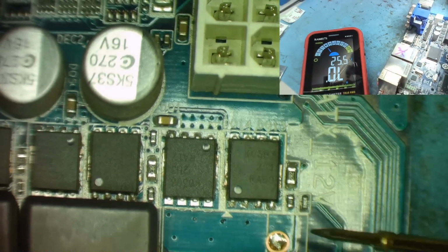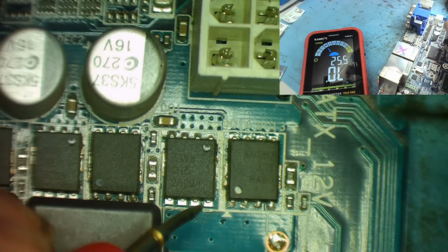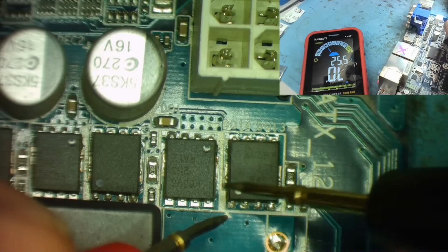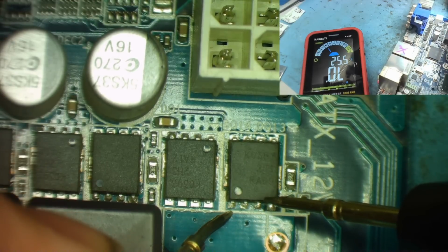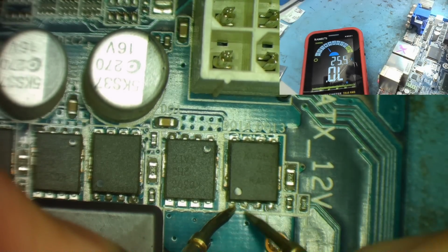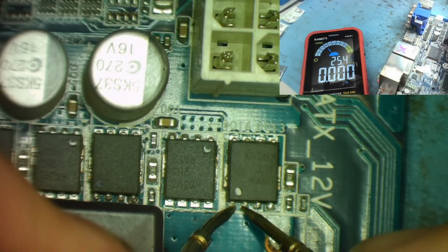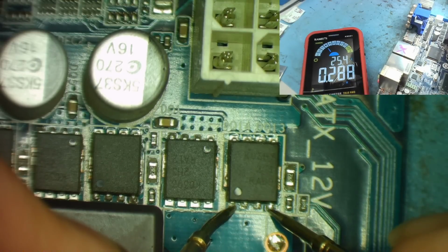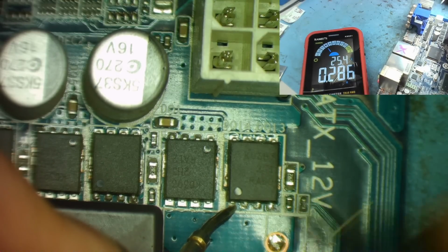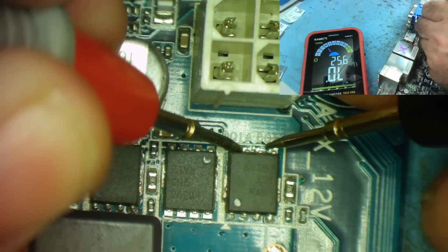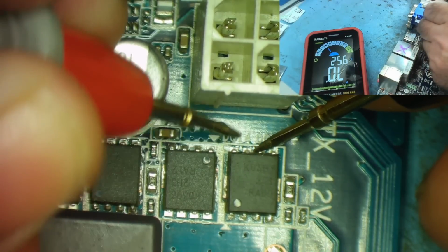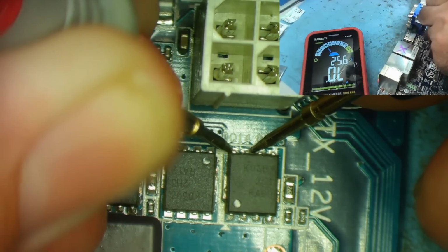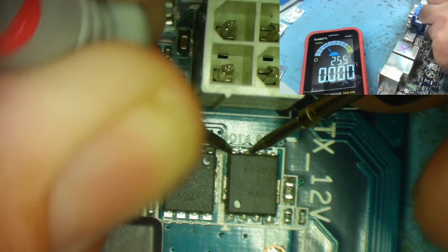And the reason is, with these, that basically 4 of them are the drain, 3 of them are the source, and the other one is the gate. So the pins are actually all connected together. If you look here, you can see, I just take the test meter. Yeah, you'll see they're connected together. The one that reads the resistance is the gate, and then the other side are all connected together. Okay, I'll just get a good connection like you'll see.